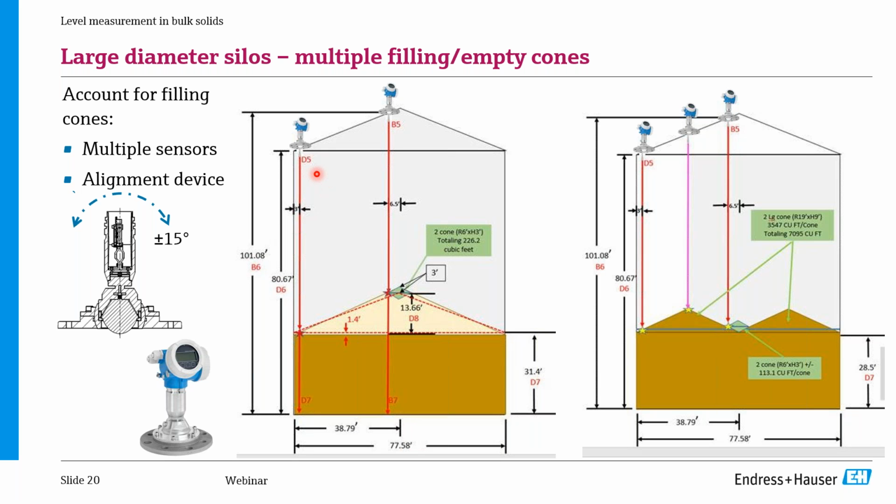So you can start having an average measurement of the level of your silo just by using one device. From my personal experience, having multiple devices spread all over your silo, if you have a very large one, is usually the best approach, because you can really have very accurate information. You can really understand all the profiling of your tanks.